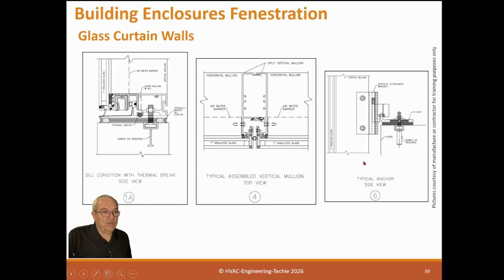It had to be a lab building where we were trying to seal the individual labs. Well, this mullion prevented us from doing that. So the rule was never, ever put a lab in a curtain wall building. They do it all the time, but they should not. It will leak between that. So if you're building a lab, don't let them put window walls in there because it will leak.